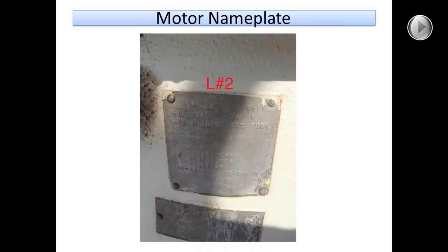This is another nameplate. This is on an older motor, and so it looks a little bit different. These older ones can be harder to read because they usually have some type of calcium or other deposits on them, and sometimes you need to scrape them off. So this one shows the pump horsepower right here. It's a 150 horsepower pump. This is the RPM, 1,775 RPM. Service factor right here. You can't read that, but I know that that's what it is. It says 1.15.